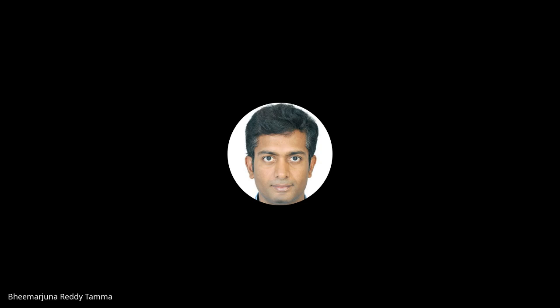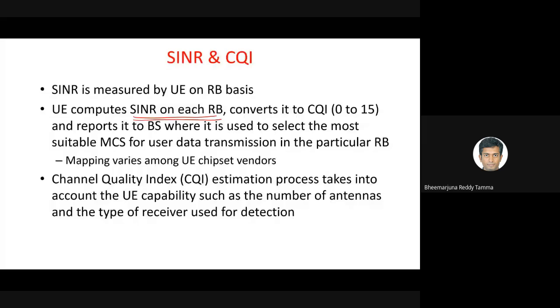Also, we have something called a CQI. So basically what we do is we measure the SNR for each of the PRBs using that power received, including the interference you are getting from other base stations transmitting on the same PRB, including the thermal noise that you are getting on a given PRB, and you convert it into the scale of 0 to 15.